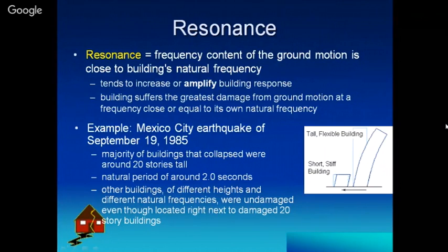And you also know that earthquake motion is due to the acceleration of the ground shaking. So whatever that acceleration is, it has some time period and frequency. The ground is also having some time period and frequency, and our building is also having natural time period and frequency. So they should not match. In case both are in phase, that the ground shaking is at the extreme end and our building is also at the extreme end at the same time, in that case there will be a resonance as per our physics law, and that is going to bring maximum damage to the structure because the forces will be very high due to the resonance.